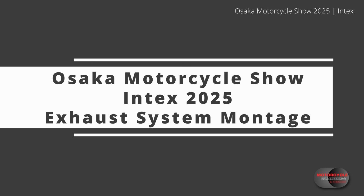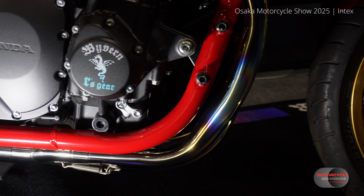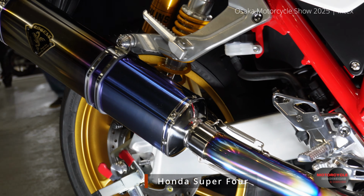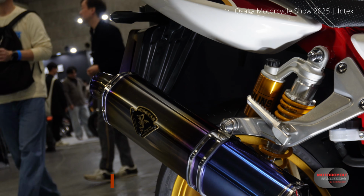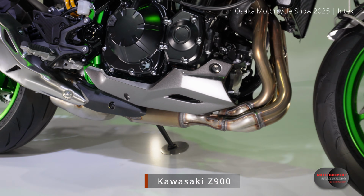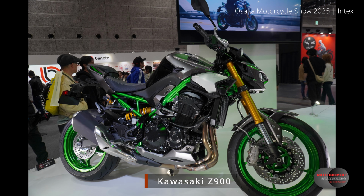And this is where exhaust tuning comes in. Ideally we want to pull as much exhaust fumes from the cylinder, dropping the pressure to increase the differential pressure from the intake into the cylinder, allowing more fresh air and fuel to come in during the next cycle. We call this scavenging or pulse tuning.